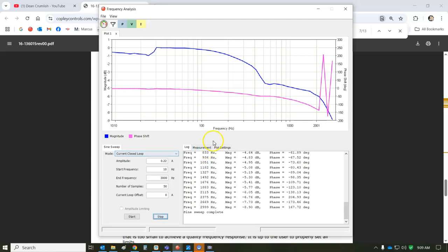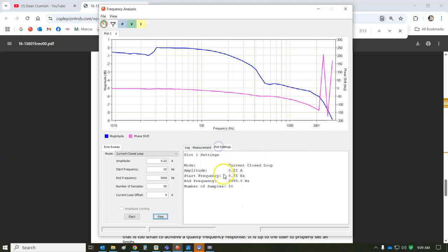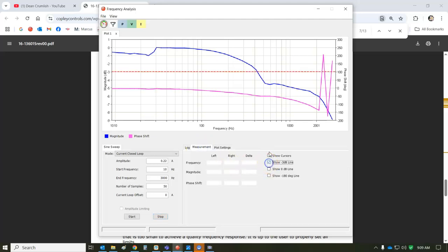So current closed loop, 0 dB. And I get a 3 dB point right about here. 1, 2, 3, 4, 500 hertz. But look what happens around 600 hertz. It goes out further before it rolls off. So I can get some pretty high bandwidth. I can get current out of this when I rotate the current vector, which is nice. There's a little half power point coming on sooner, but I can still go wicked fast with this motor.